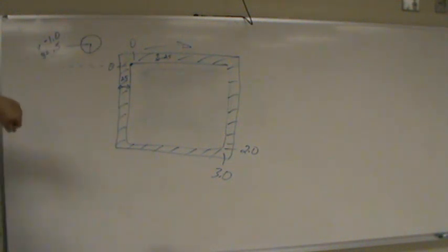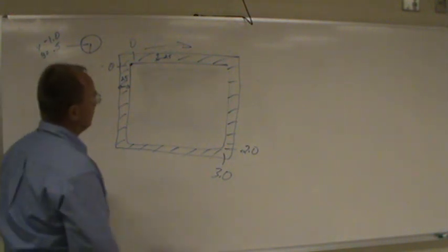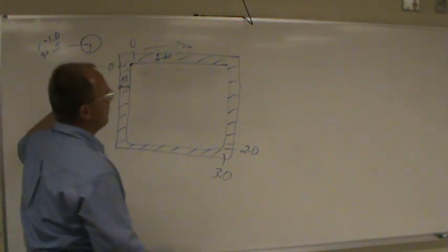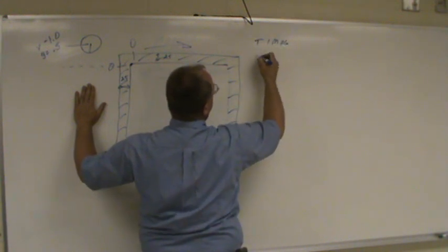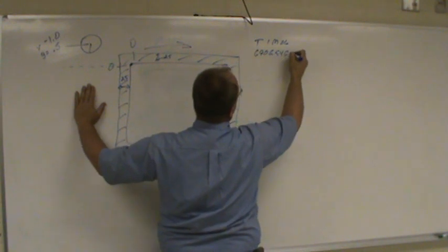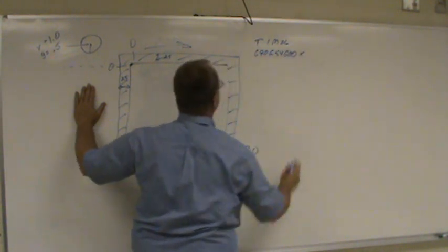Okay, so now to get into writing our program, you have those first 4 lines: T1 M06, G90 G54, G00, X be your start point.